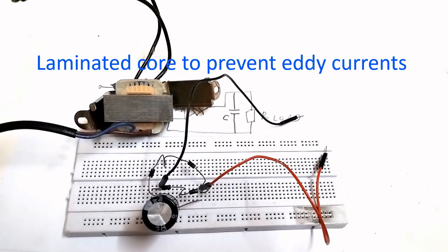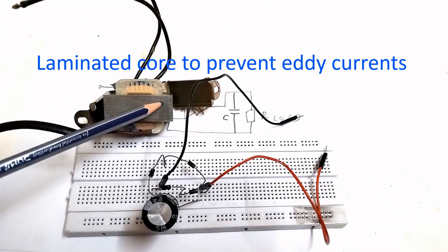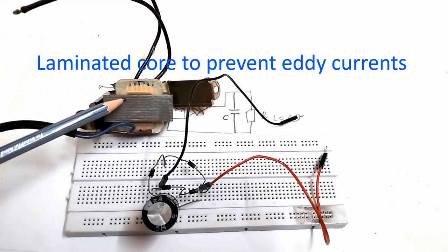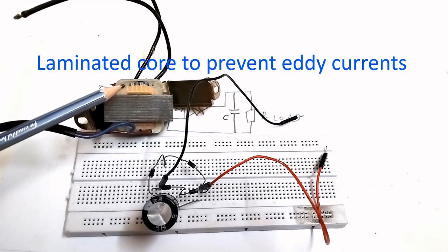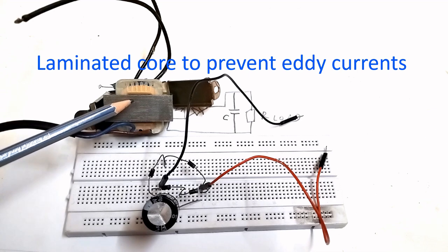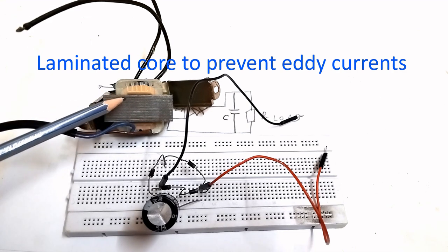I have just removed part of the cover of the transformer just to show the laminated core. You can see that this core is made of several laminated sheets, and the lamination is needed to prevent eddy currents. The core will have eddy currents, which will heat up the core, and that can be prevented by using a laminated core. When eddy currents are there, that will cause generation of heat and loss of energy, so that the efficiency of the transformer in converting the power will be reduced if you use a core without lamination. A core with lamination will improve the efficiency of the transformer.